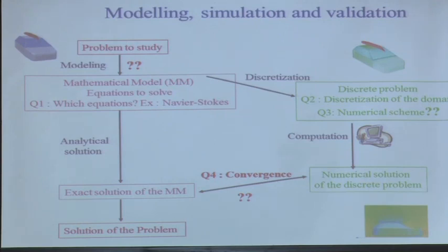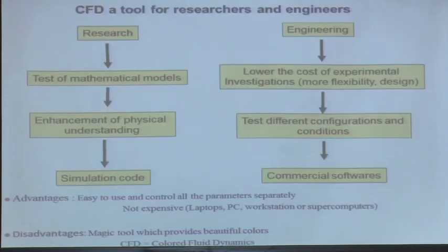This is one of the first steps of CFD: to check that your numerical algorithm, your code, your software is able to give you convergence, to be sure that you are converging to something. And then you have to test if this solution is the correct one on some analytical solution. So you can check what the error is and the rate of convergence.